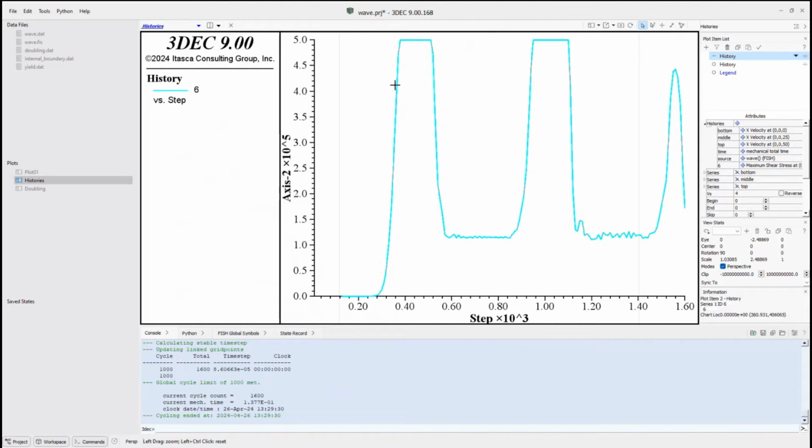The shear stress increases, and it can only get to that maximum 5 because that's essentially equal to the cohesion. It can't increase more than that. The zone turns plastic, wave comes back down, and then same thing happens on the way back up again. Or potentially on the way down. So you can see the effect of this yielding zone. It definitely does cause distortion of your waveform and other interesting effects.